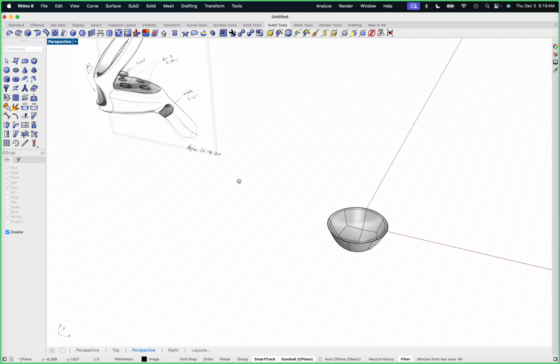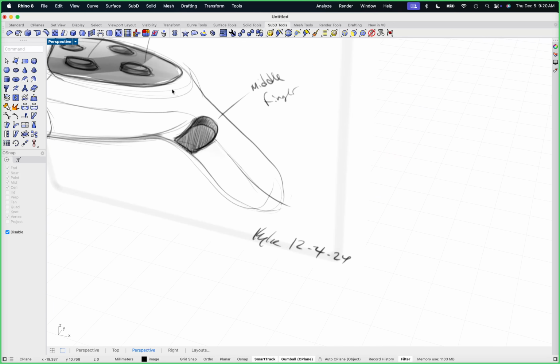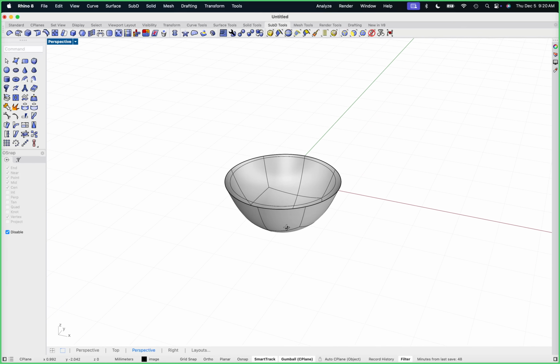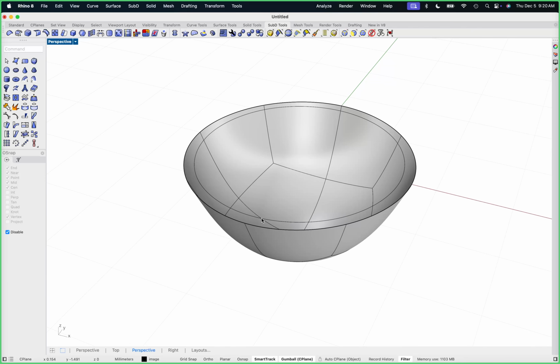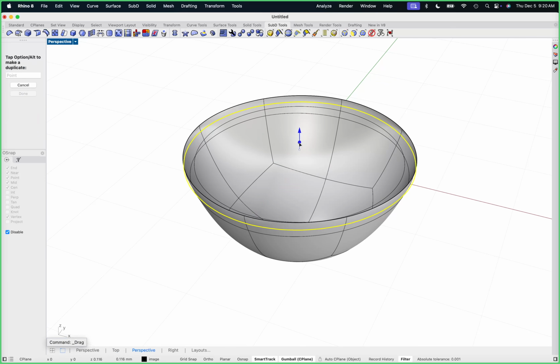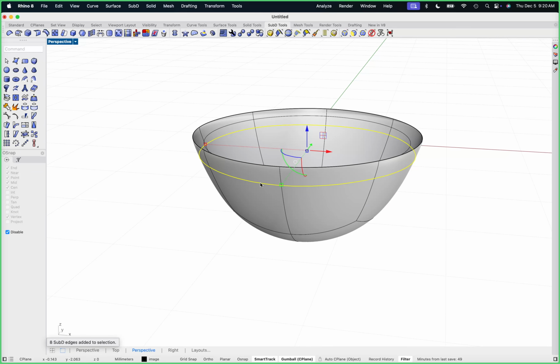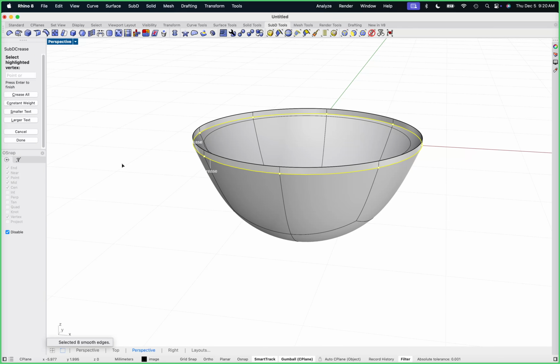because we're going to do a lot of messing with this later. There's a slight flange on the top of this thing before it goes into this little disc. So what I might do is start with that, and I'm going to extrude straight up, and then I'm going to crease this edge. I'm going to use the crease tool here, and we're going to crease all.